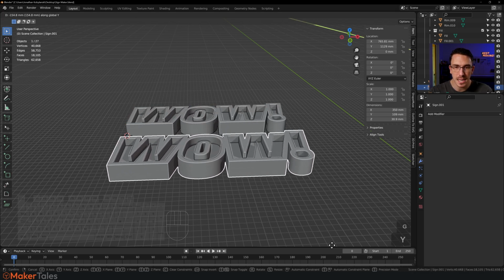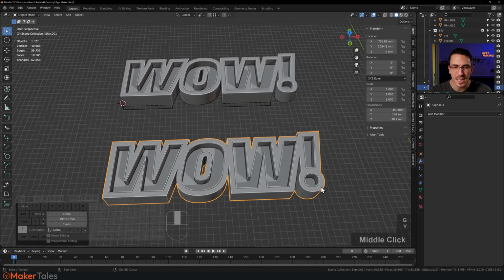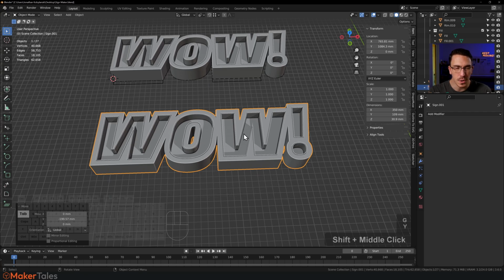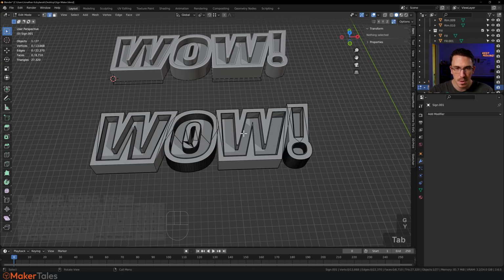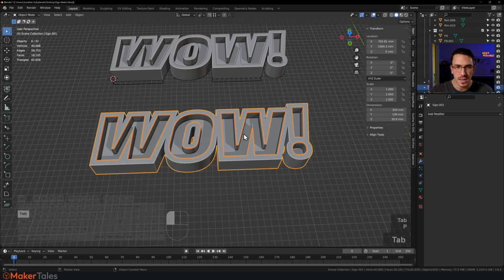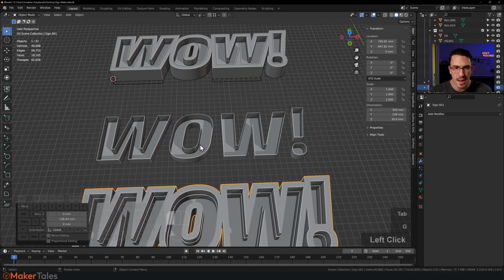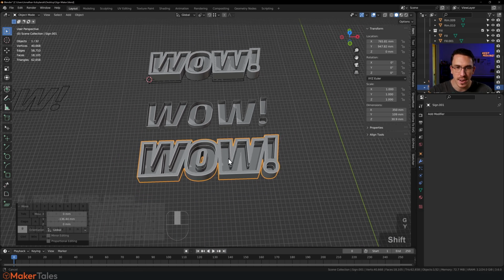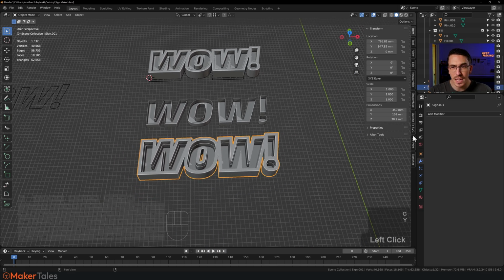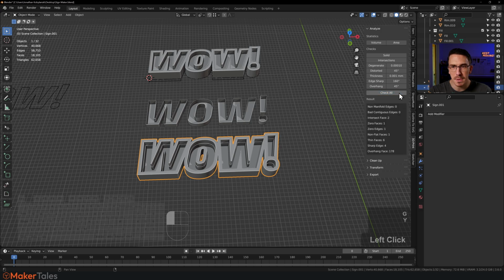So once that's been done, now you'll be able to see this here, and we're going to go into edit mode with tab, press P, go loose parts, and now we will have this as one word there, and we'll have that as one word there. Now, let's just quickly give this a 3D print check. There might be problems. Oh no, look, perfectly clean, ready to go, and I'm sure those are perfectly clean. Those are very simple shapes.